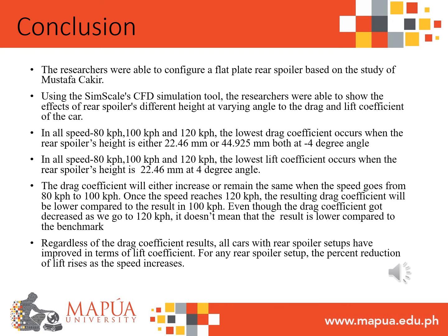Based on the results, we can also conclude that the drag coefficient will either increase or remain the same when the speed goes from 80 kph to 100 kph. Once the speed reaches 120 kph, the resulting drag coefficient will be lower compared to the result at 100 kph. Even though the drag coefficient decreased as we go to 120 kph, it doesn't mean that the result is lower compared to the benchmark.